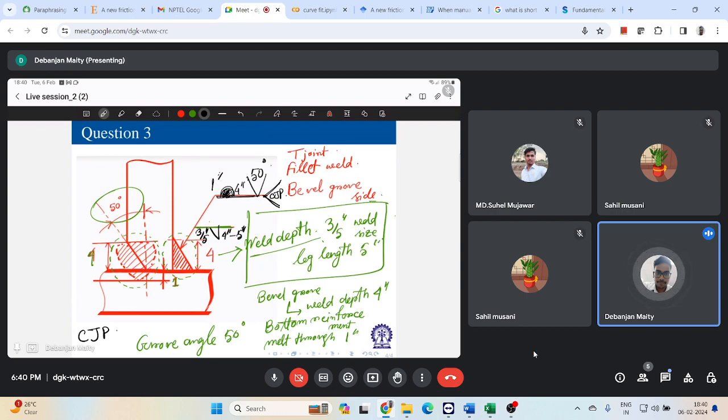There are a few extra things, like you can have straight arrow lines and broken arrow lines. A straight arrow is basically used for the weld location, whereas the broken line is mainly used for joint preparation, and it basically breaks towards the piece that is to be beveled. So if you have some bevel kind of joint, you use that broken arrow line towards the piece where you are doing the beveling.